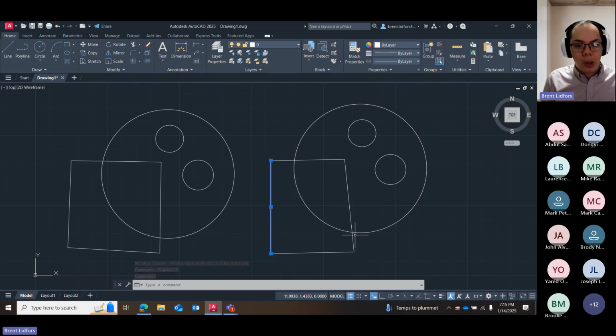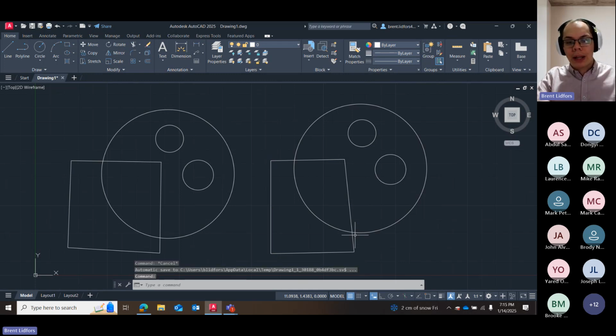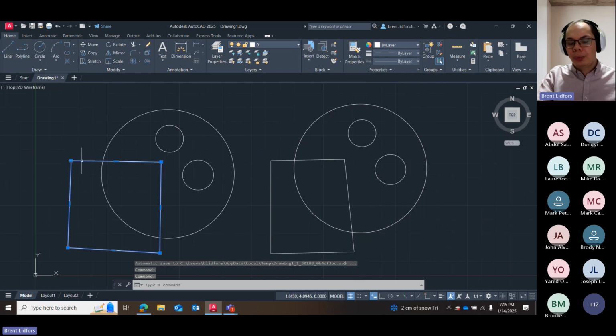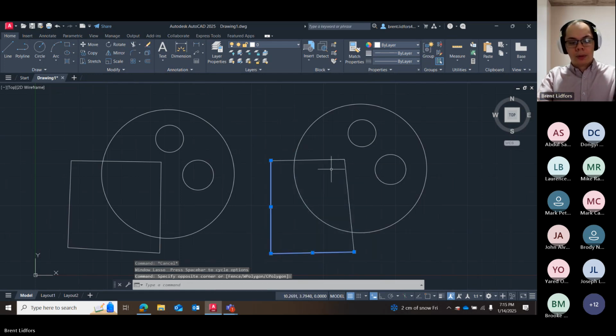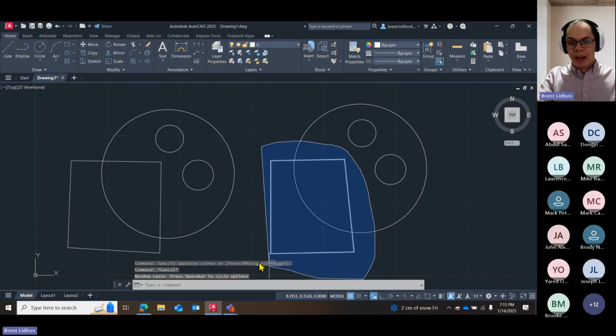So there are reasons why you'd want to use polyline over just standard lines. Because with this one on the left with polyline, I can easily just pick it and it gives me the whole object. This one here, I have to manually get all those sides, or focus a little bit more when I go to select it, to accurately grab that one tool, or that one rectangle.